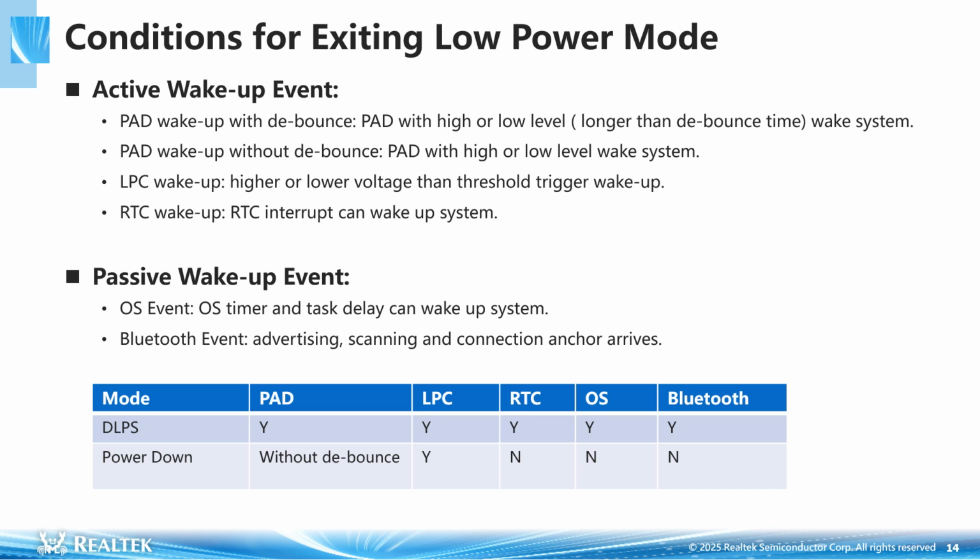It is necessary to ensure that related events are successfully configured before entering low power mode. In DLPS mode, PAD, LPC, RTC, OS, Bluetooth events can wake up the system. In power down mode, only PAD, without debounce, and LPC events can wake up the system.